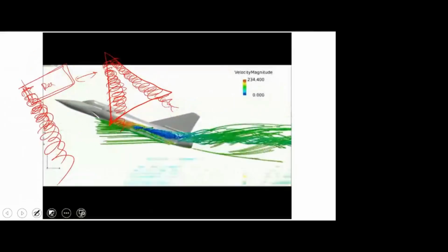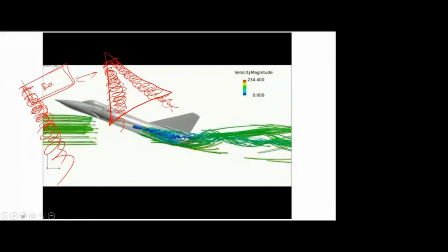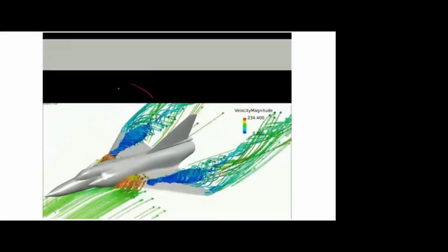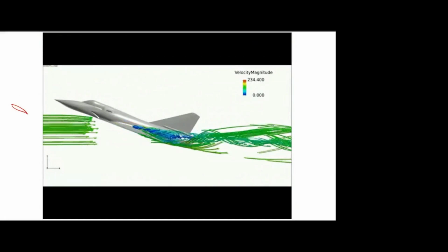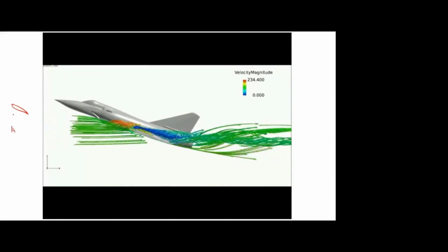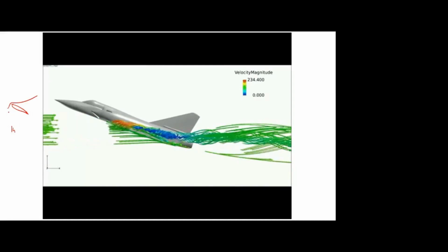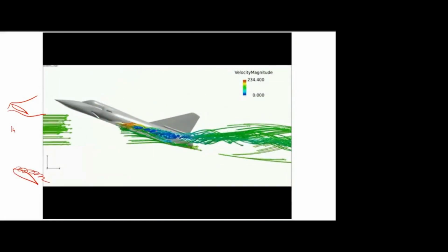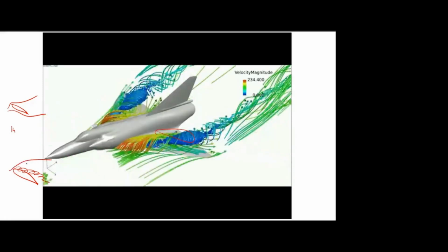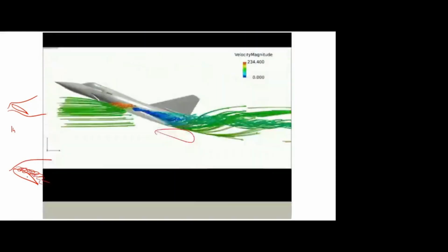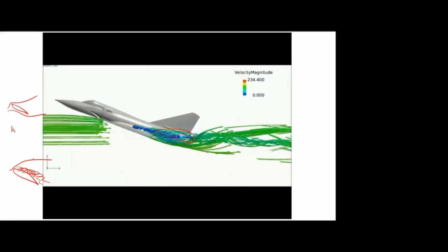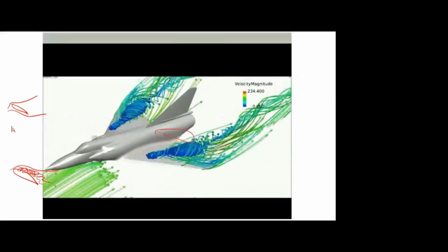So another important thing, I will write here. Normally if you take the rectangular wing, maybe at 14 degrees, 16 degrees, what will happen? It will separate. But if you take this delta wing, there are strong vortices on it, with a low pressure region. This low pressure region sucks the separated flow. These are the axial vortices on the delta wing, which have very low pressure. This low pressure sucks the separated flow. So instead of separating, the flow stays attached to the surface.